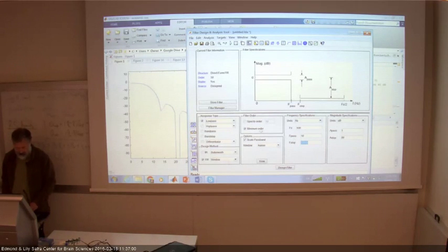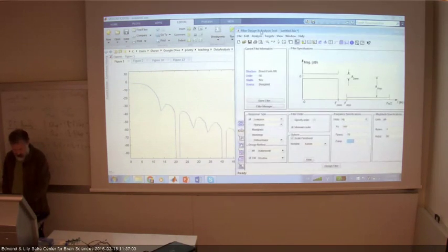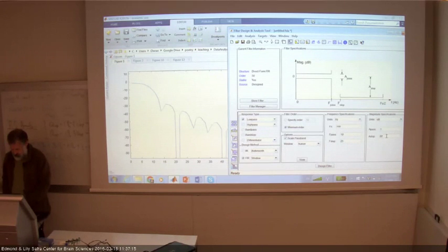Okay, the f-stop. I need to select an f-stop. Let's say it's wherever I'm below minus 40 dB, so this would correspond to about 25 Hertz. And the attenuation at the stop band should be below 40 dB. So what I design is something that has a corner frequency at 10, drops to 40 dB at 25 Hertz, and it's below 40 dB above that. These are the design parameters for the filter that I read from that. So I design the filter.